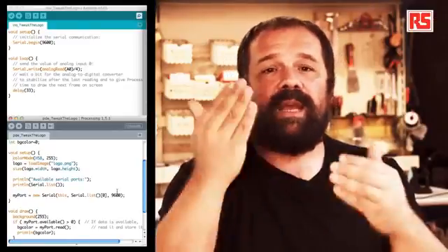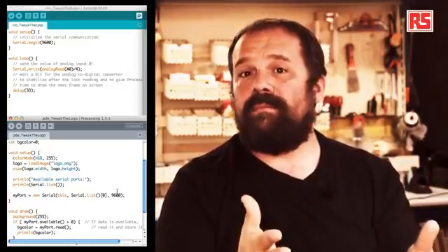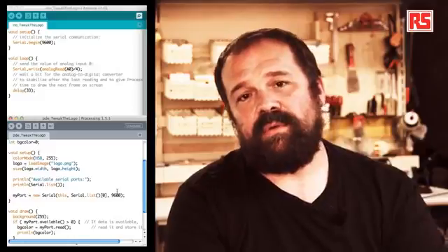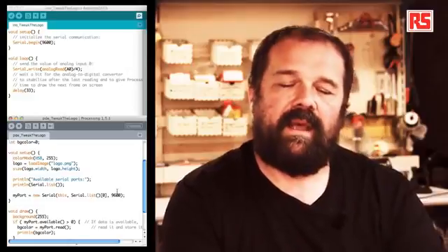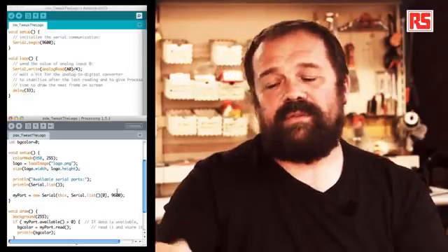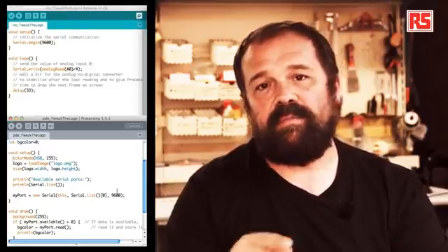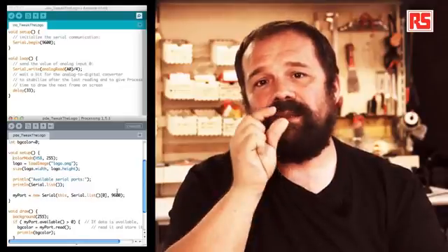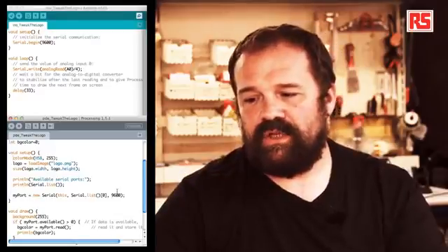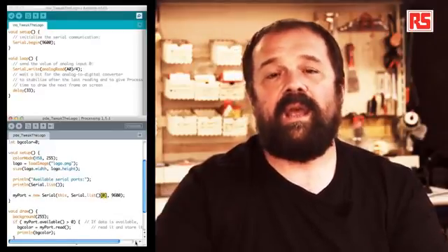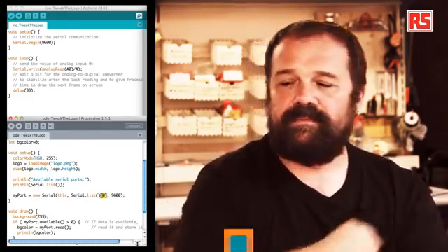While on Windows, we get a list of COM1, COM5, COM3, COM19. The actual COM ports that you get on your computer change depending on your computer, where the Arduino is plugged in, and a number of other factors. So you will have to use the output of Serial.list and what you see at the bottom of the screen on processing to determine which one is the port that you need to use. And then you change in your code, you change the 0 here that I am highlighting with the number of the port from the list that corresponds to your Arduino.